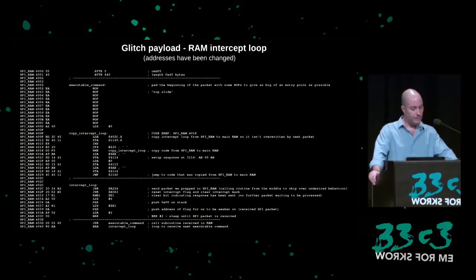To try to maximize chances of success, I looked through the ROM code for multi-byte instructions, which if broken up would have contained within them a jump opcode with a destination that should lead to where my executable payload was placed in RAM. Since the ACP has a single address space, this gives a lot of opportunities for glitching to cause execution to reach the payload.